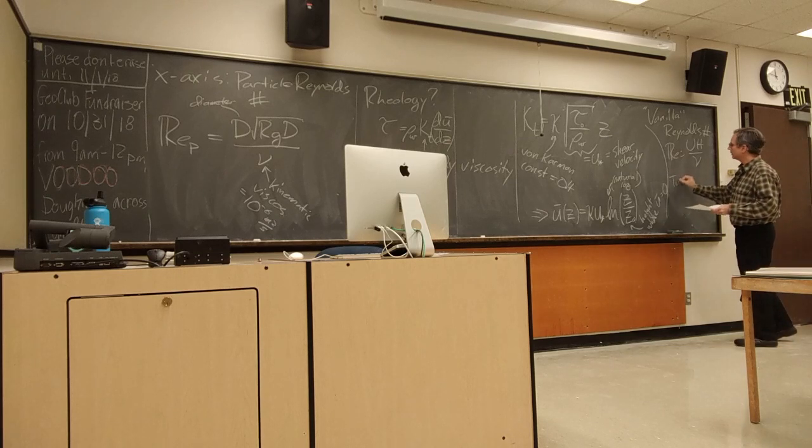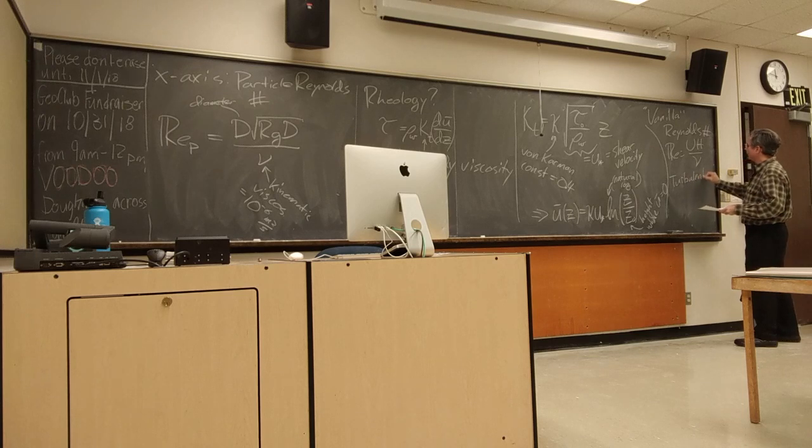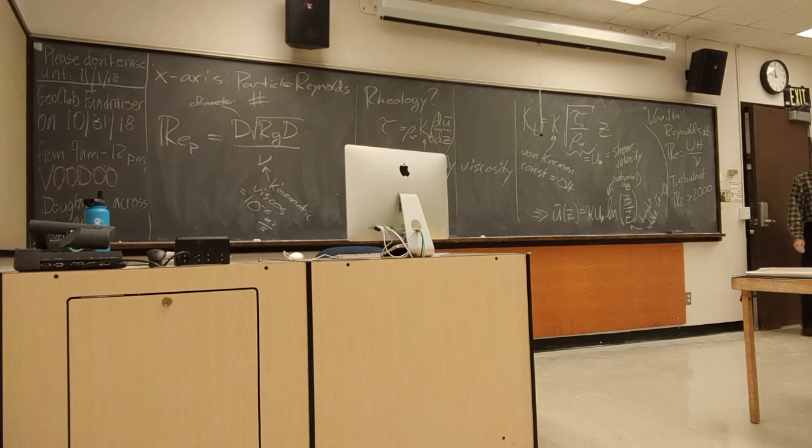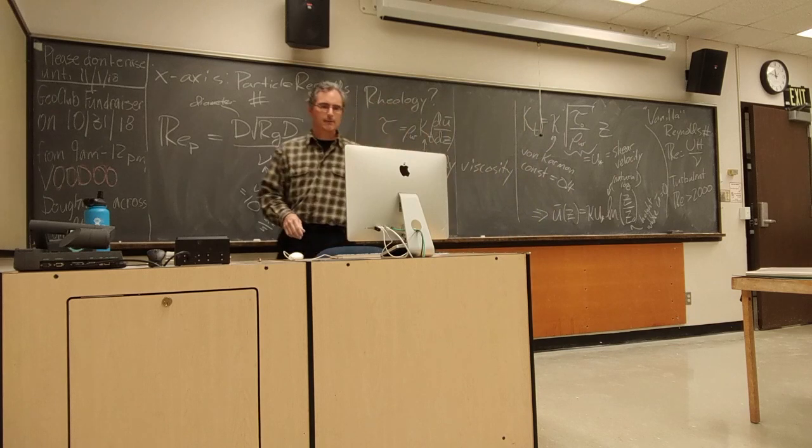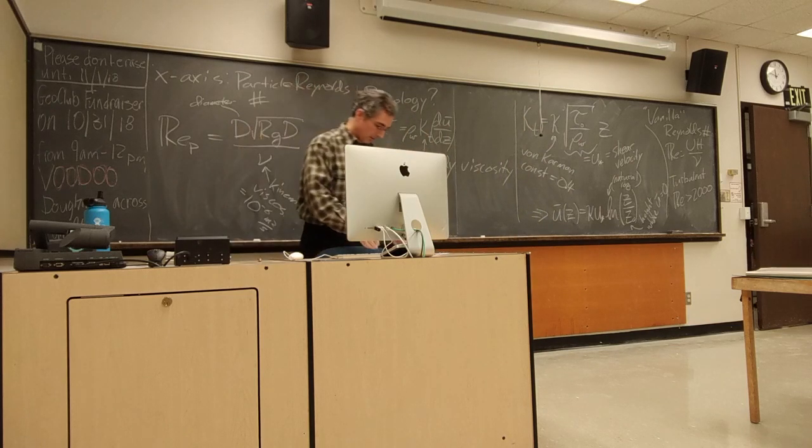And turbulent is when the vanilla Reynolds number is greater than 2,000. It's always turbulent. Like I said, for this particular case, I came up with 2.5 times 10 to the 5th for my actual Reynolds number, quite a bit greater than 2,000. Almost any flow you ever see on the surface of the earth is going to be turbulent. Of water. Not of oil, but of water. All right. That's that. I know that was a blast. I went through that all real fast, but we'll take a breath next time.